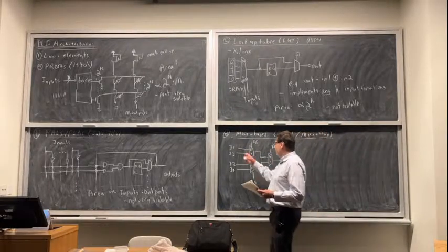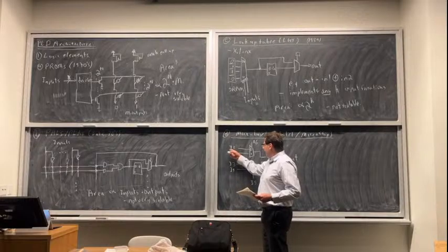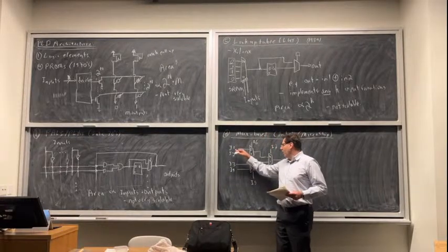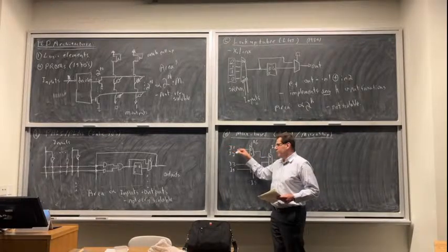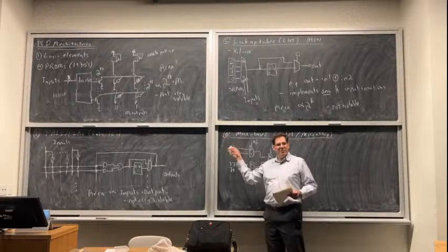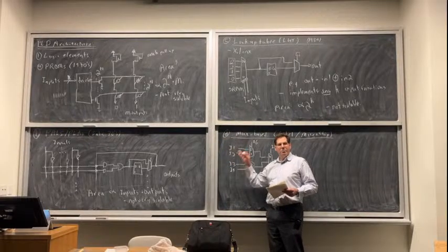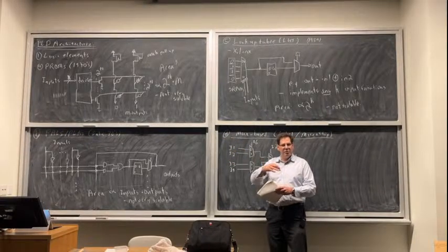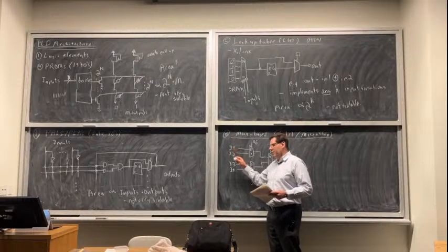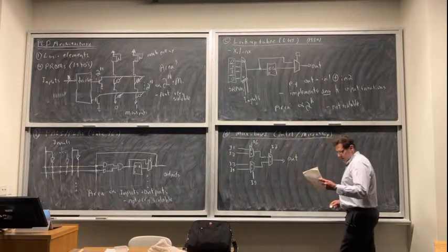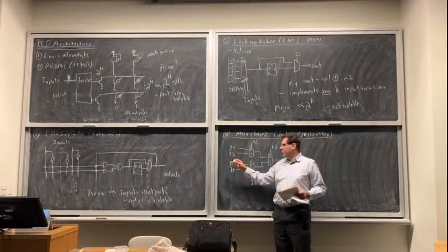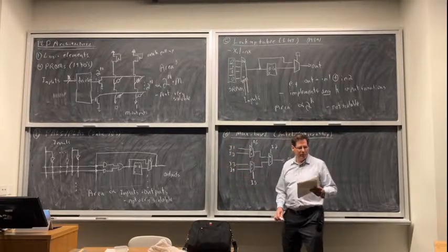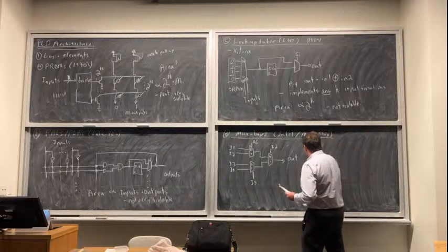The other thing that's important to know is that I can connect these inputs to some signal, but they also can be connected to power or ground. So they build the programmable switching to bring signals in. This could be something coming from the programmable routing, or power or ground. You do that just by having a few more programmable switches, and that's true of each one of these. Turns out that's important. If I can't connect it to power and ground, this might be difficult. But I can basically make these inputs power or ground if I want. So let's say I want to make this function.